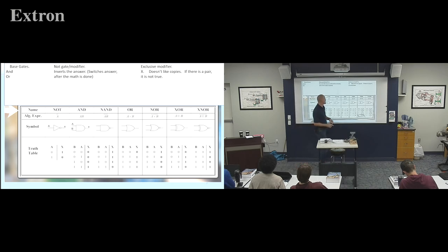You only see the exclusive OR, and they'll flip you over and say the exclusive NOR. So you can put both prefixes on. We'll go to our exclusive NOR gate. For exclusive NOR, it says, okay, first we're exclusive. It is if I see either or, but exclusive, and then I'm going to reverse the answer.